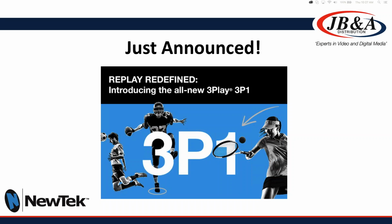Some other really nice things about it, if you do plug in SDI cameras, they will get turned into NDI sources. So this not only could become a replay system, but can also function as a 4-input module into your production as well. So for example, just imagine you have, let's say 8 cameras coming in for your sporting event. You could plug 4 directly into the TriCaster, 4 directly into the 3-play system, and all 8 of those cameras will be available for switching in the TriCaster, while the 4 that are plugged into the 3-play will also be available for instant replay. So gives you some additional flexibility there.